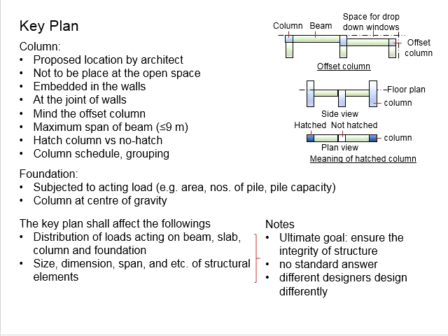In this case, it will be better for you to construct a combined foundation. The center of gravity of your combined footing should be in line with the center of the loads, as the resultant of the two columns that it supports. This is something that you need to take into consideration.